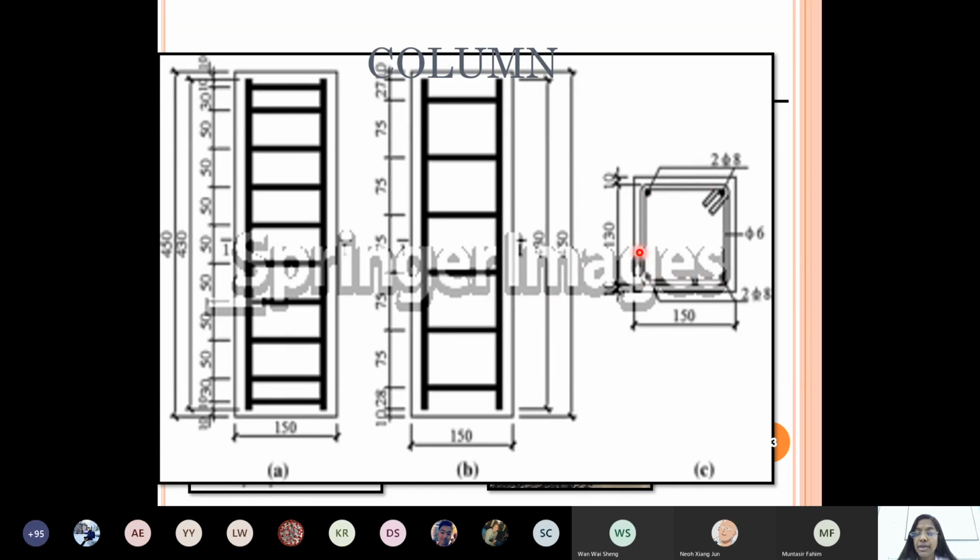And then the connector or the secondary bar, which is acting as a tie member, is called as these things. The spacing also you will design. So it is like a box type, covering all the four rods. This one, two, and on the other side, perpendicular to the slide, you can see other two bars at a distance. So all these four bars are held together, forming a reinforcement by these types of ties. That is called tie reinforcement.